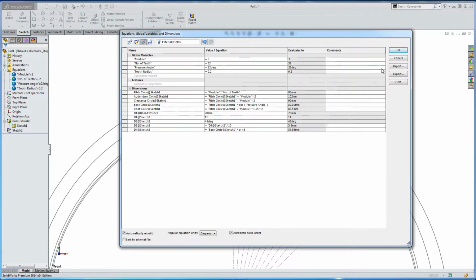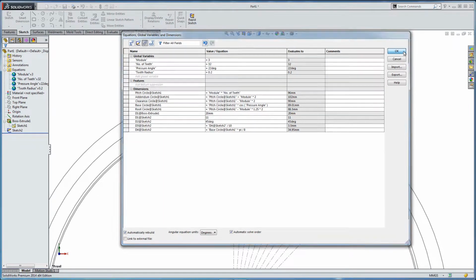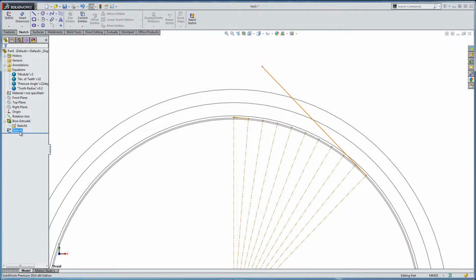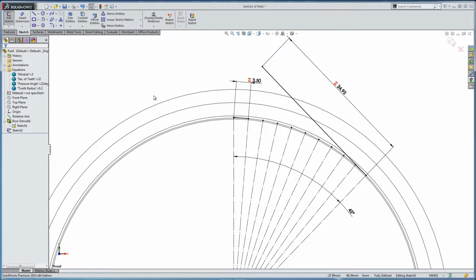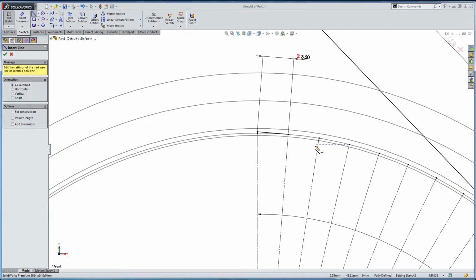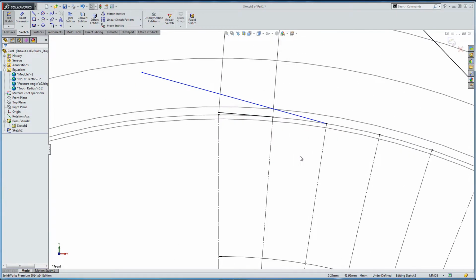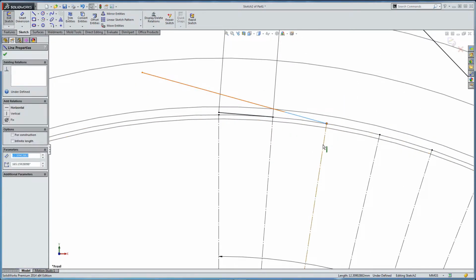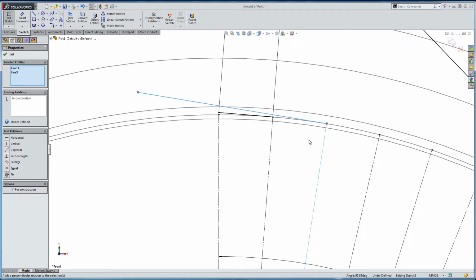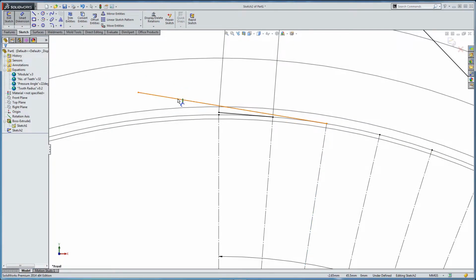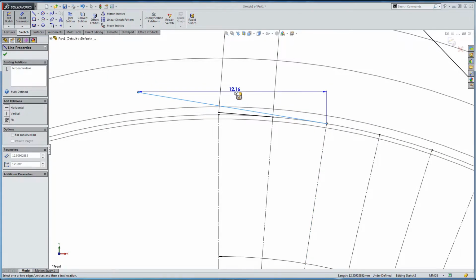Okay, and the reason why we need the circumference is because we're pulling a taut piece of string away from the start point of where our involute is forming. It's going to start to make sense in a little while. We need some more reference lines. All these reference lines we're now inputting, they're going to be perpendicular to the initial geometry that we built in our pattern, circular pattern.